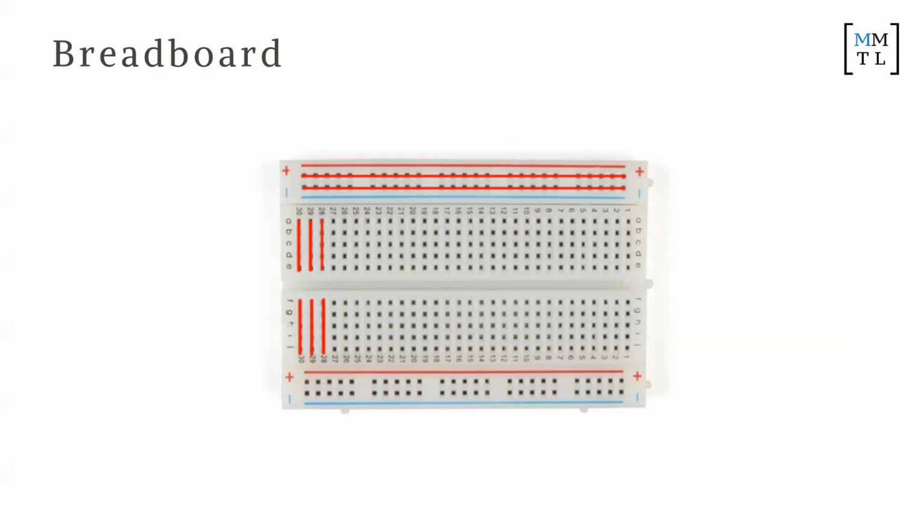So this is back to ground. Again, best practice is to put this on ground, for example, then make another connection from this going up the line. If you make that connection, then it'll be good. It's just good practice, because it's very confusing if you connect it straight back into the Arduino, particularly for complex stuff.